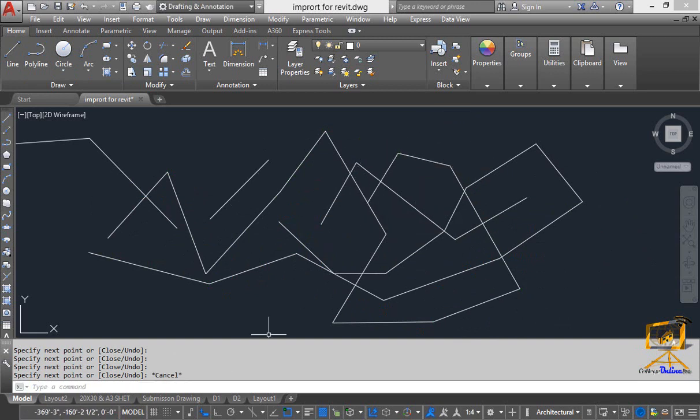We have also discussed how to draw a line using the command line. In the next phase we discussed how to draw a line using the shift at the rate option by specifying a specific angle and length. And we have also used the dynamic input option, on the basis of which AutoCAD guides us by dynamically entering the length and angle. After specifying both length and angle, just press enter at the end and the line will be drawn. Hopefully this video will help you a lot.